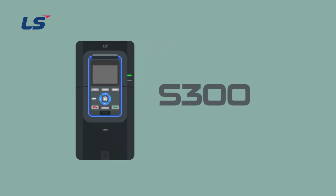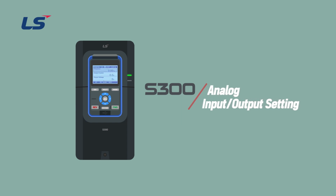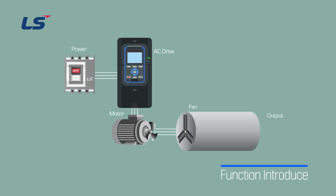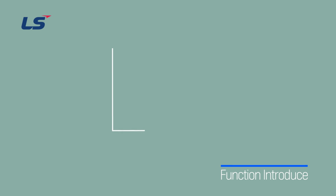Hello! In this video, we will explore how to set up analog input and output for the S300. First, analog voltage and current inputs through the AC drive control terminal can be used for various commands such as setting the operating frequency or torque command, and can also be utilized as feedback for PID control. However, depending on the load system, the minimum and maximum values for commands or feedback may vary.